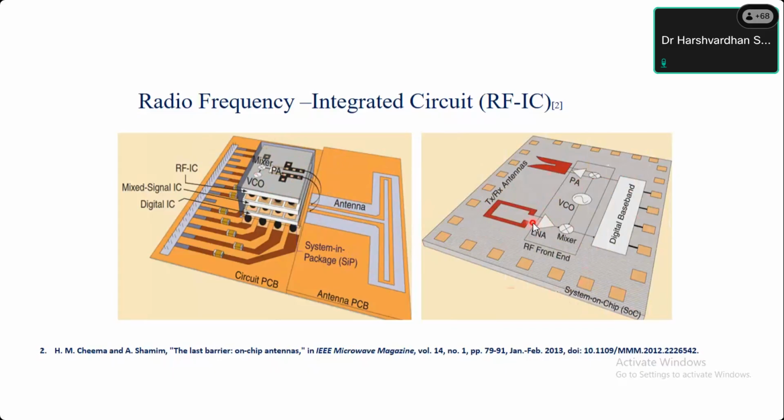Now here, with any impedance, the connector impedance matching is not required. Directly you can match with the LNA. So that impedance matching requirement is eliminated, at least the 50 ohm impedance matching.